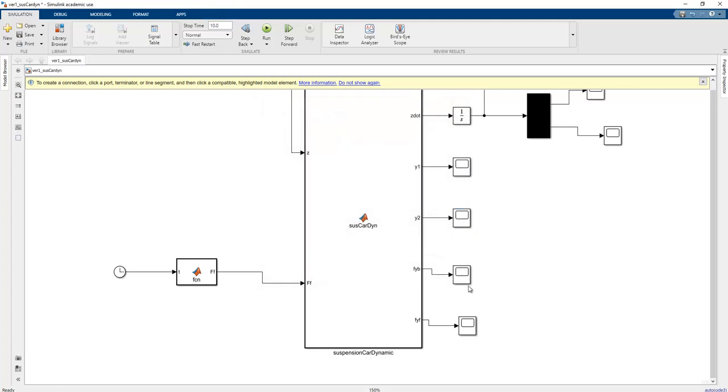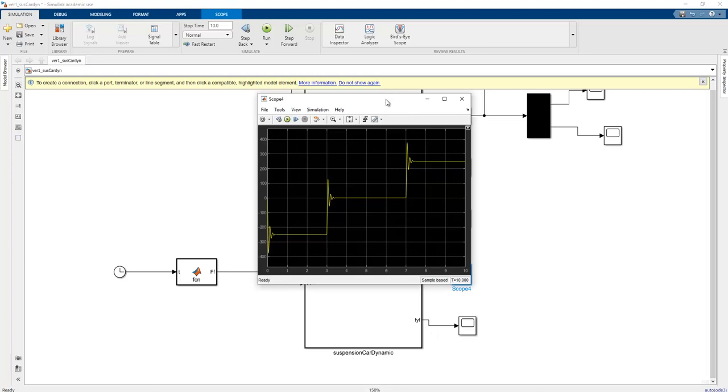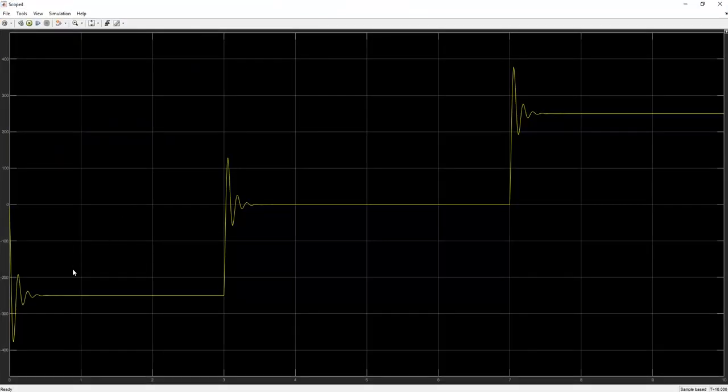And so what about the Fyb forces in here? Fyb is the back reaction force, and so this is up to minus 400 Newton. And so it can be said that this suspension system should not be broken under the 400 force in the running position, okay?